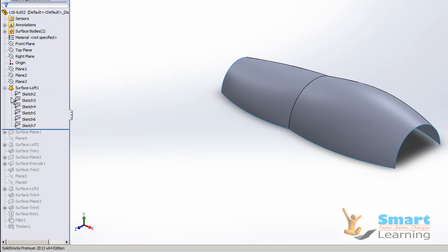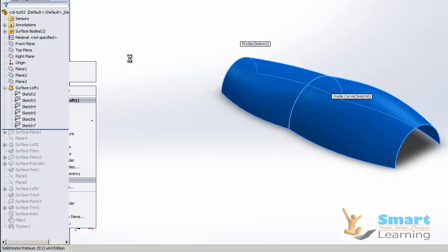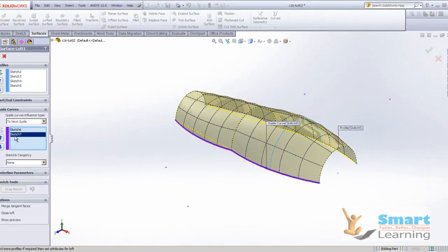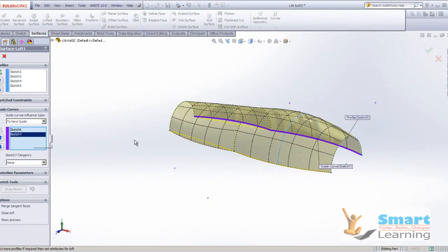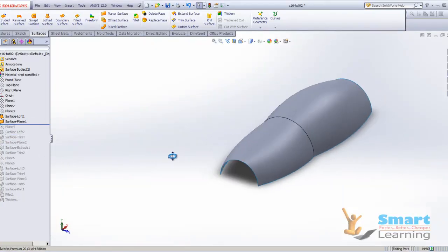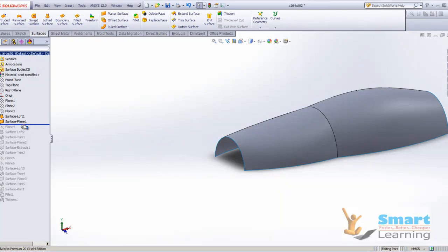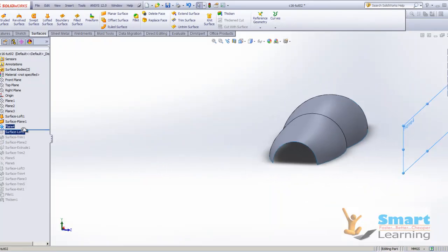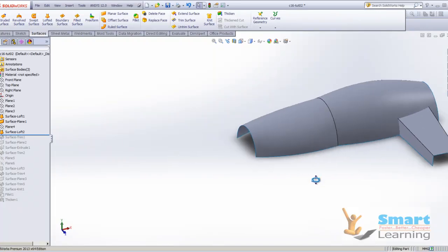So after that you can directly create the lofted surface where you are going to create all these 4 surfaces and guide curves this side one, then that will be matched. So all these 4 guide curves in one direction and 2 side curves at the base will be the other direction. Then we'll go for the surface to patch this. Again we are going to create a plane here so that the handle can be extruded and added here.